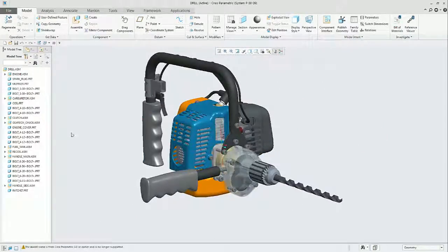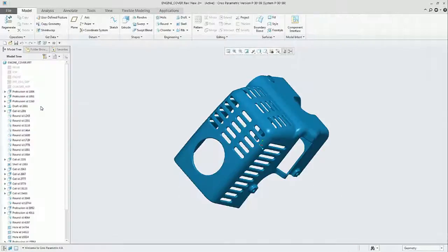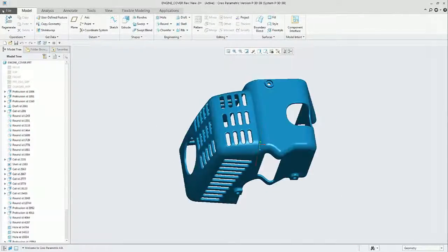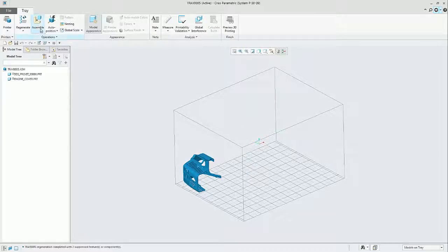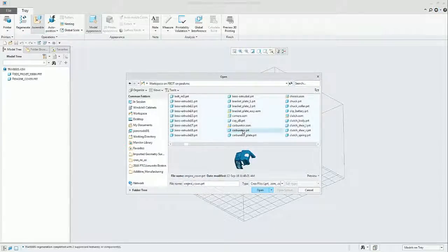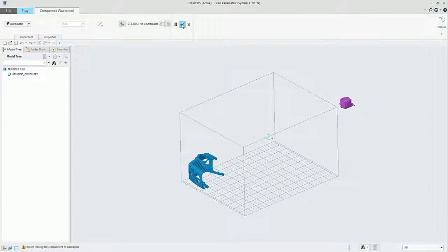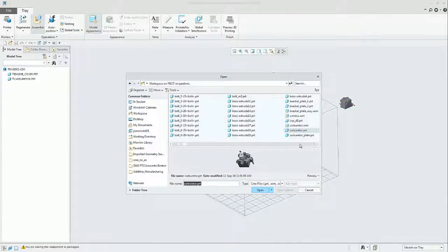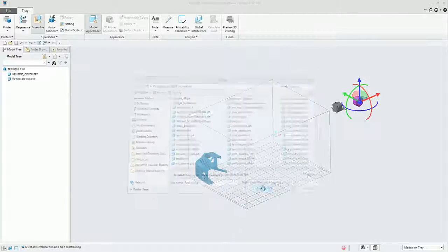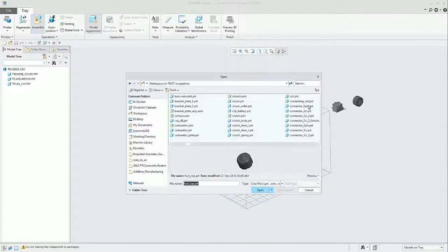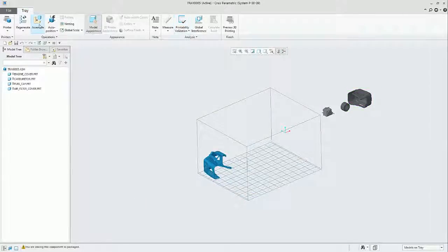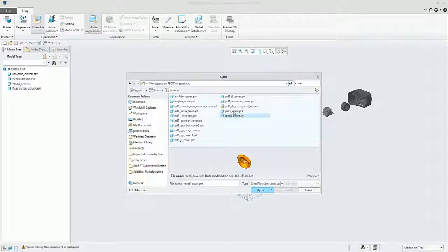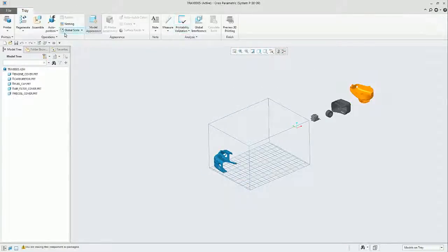To explain the basics of tray assembly, let's start with one part. We can go to File, Print, Prepare for 3D printing of that particular part. Click on Auto Position and Assembly other parts. We can just place other parts, as many as we want, into the tray, even if those parts are not over the bed. This can be placed later using the auto positioning.